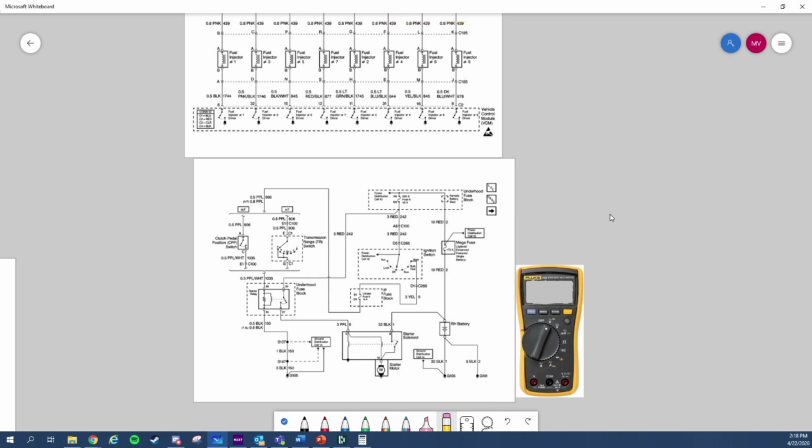Yeah, I'm pretty sure there's a loose connection, maybe internally or maybe at the switch, because the polarity is usually switched through the actual switch itself. If you have the meter, I would check the wires end to end and do a wiggle test, so pretty much just move them around and see if that beep goes down, or even check the resistance, because if you have a loose connection or loss of connection, it will not work at some angles, like you said, because more than likely it's opening and closing the circuit.